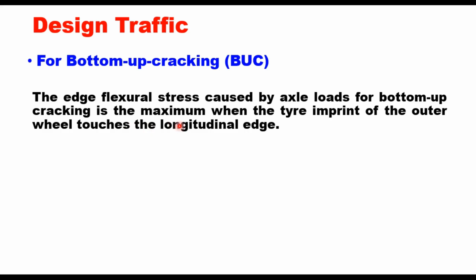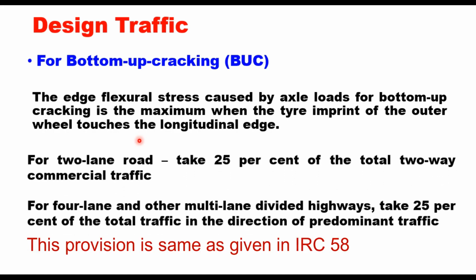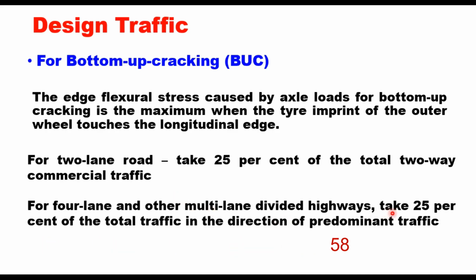For bottom-up cracking, the edge flexural stress caused by axle loads is the maximum when the tire imprint of the outer wheel touches the longitudinal edge. Practically, very few wheels of vehicles are tangential to the longitudinal edge or longitudinal joint of a road. Therefore, for a two-lane road, take 25% of the total two-way commercial traffic, and for four-lane and other multi-lane highways, take 25% of total traffic in the direction of predominant traffic.